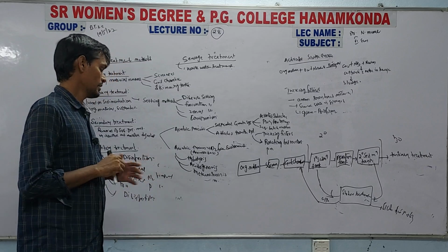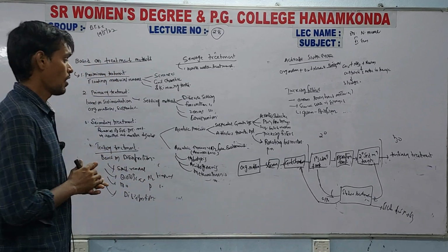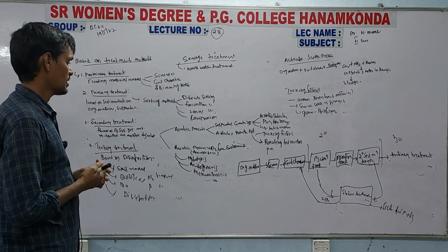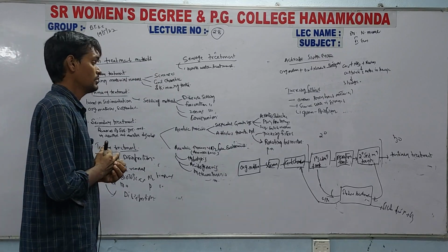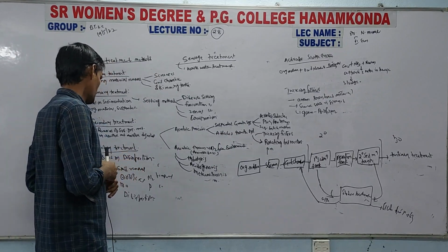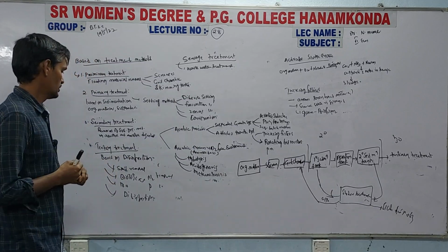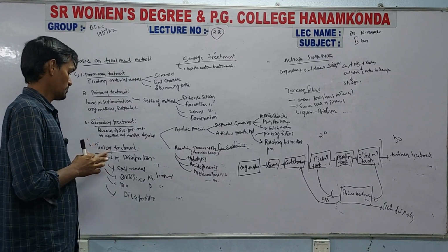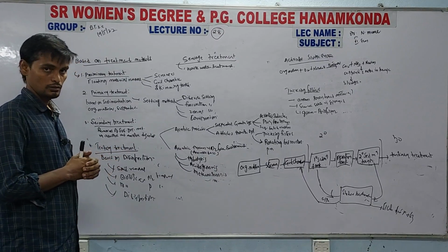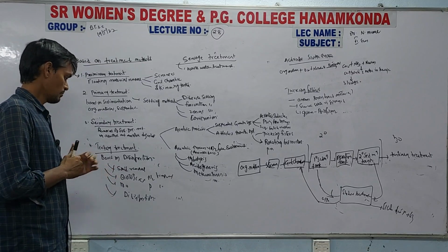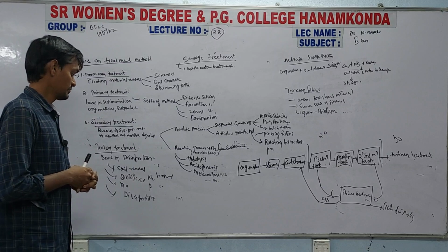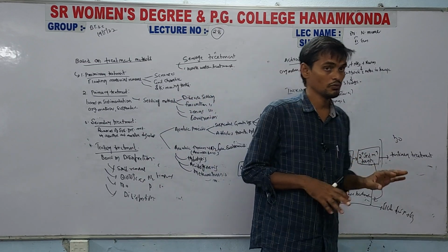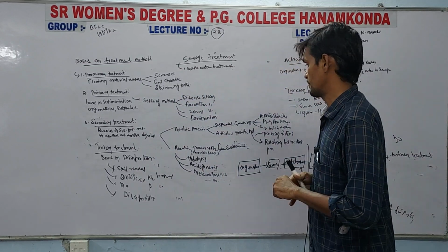Next, coming to the anaerobic process, it is done in an oxygen free environment by using anaerobic bacteria, through hydrolysis, acidogenesis and methanogenesis. Next, in tertiary treatment based upon disinfection, we have solid removal, biological nitrogen removal, biological phosphorus removal and disinfection method. So, this is all about the different methods of sewage water treatment.